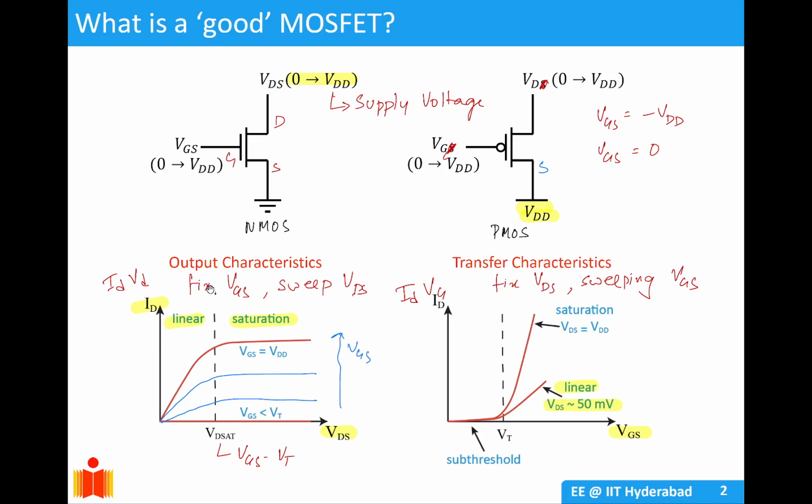For this you fix your gate voltage and you sweep across your drain voltage, and you see how your drain current changes. You get some curves like this, where you have a linear regime for small VDS and a constant current for high VDS, which is your saturation regime. And as you change your VG values, your curve increases or decreases depending on your VG values.